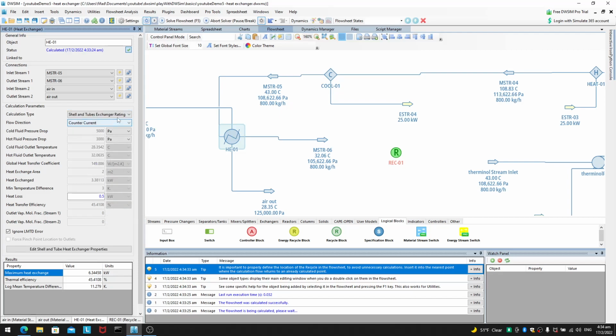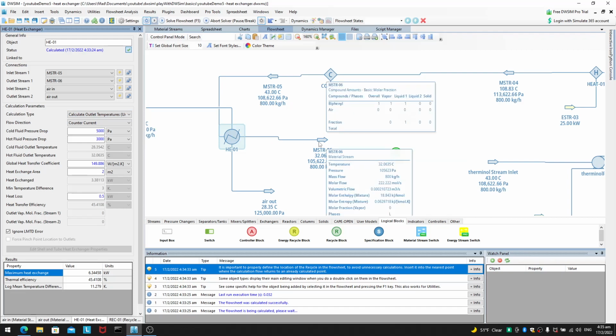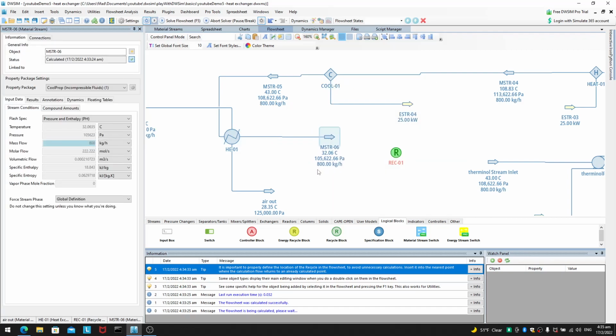The other thing I forgot to mention is that pressure drops are normally also very much dependent on Reynolds numbers. You should not manually define them, unless you already know what your flow rates are and you want to fix your flow rates. But for a realistic scenario, you will need something else to calculate the pressure drop across this shell and tube heat exchanger.